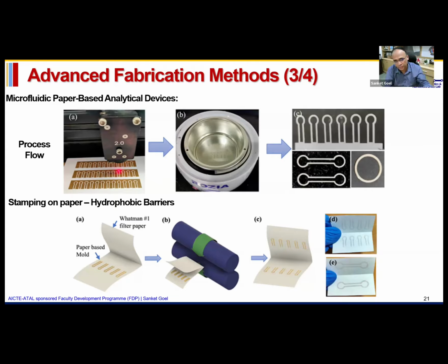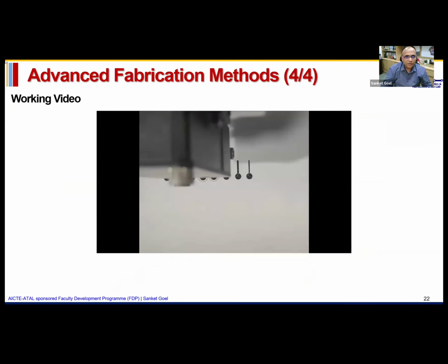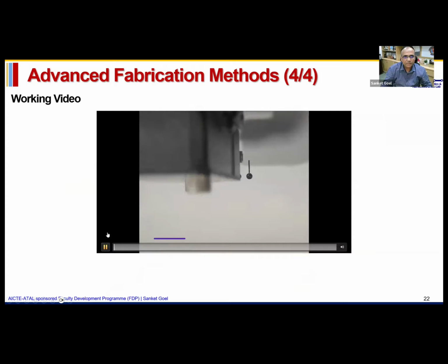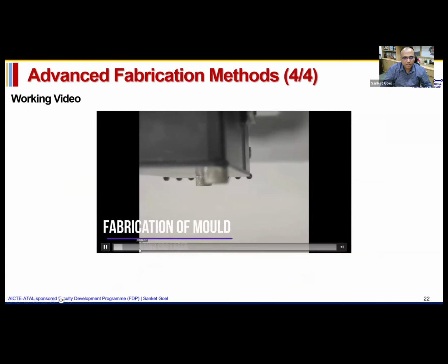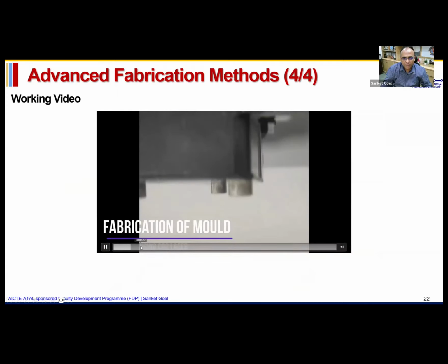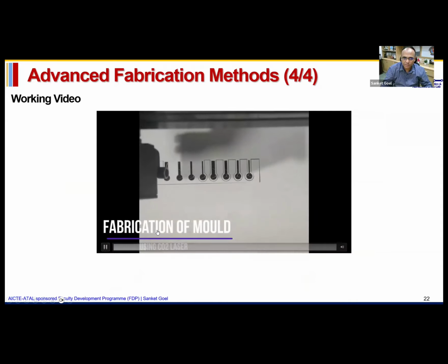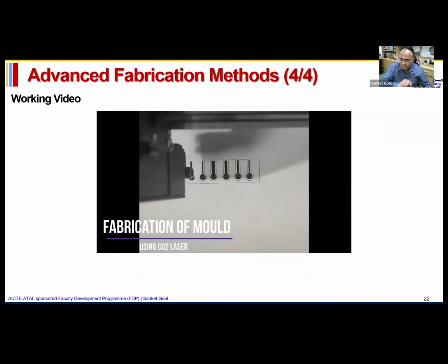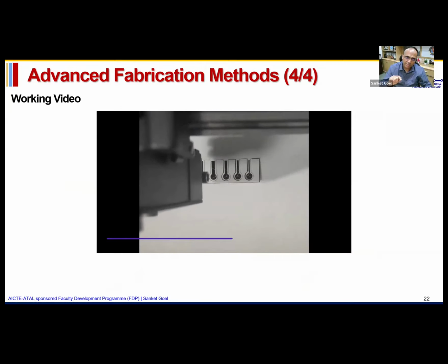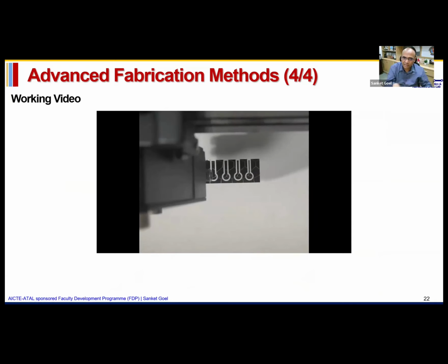All of them are published work from OpenLab. So this is a quick video which talks about how we can create a mold and how we can create multiple microfluidic devices. So you can see that this is how we have created the mold. We can cut those polymeric devices using a laser cutter and engraving machine.